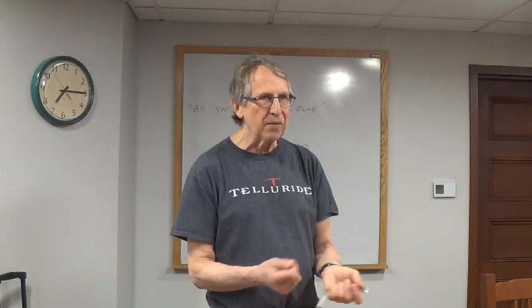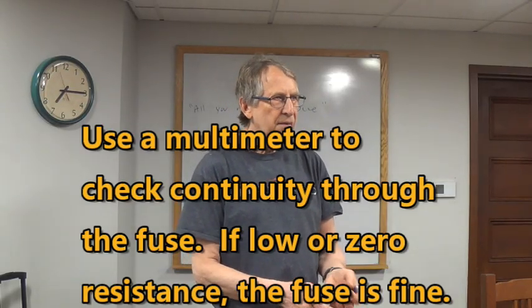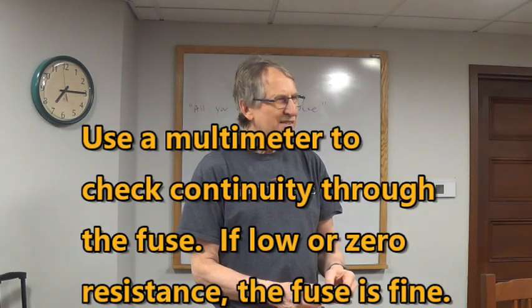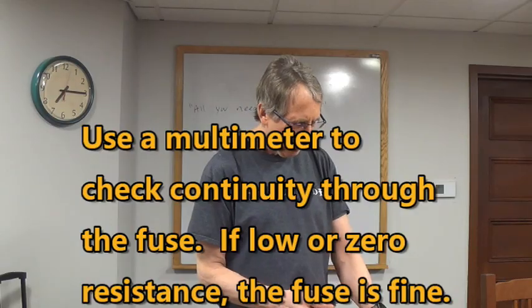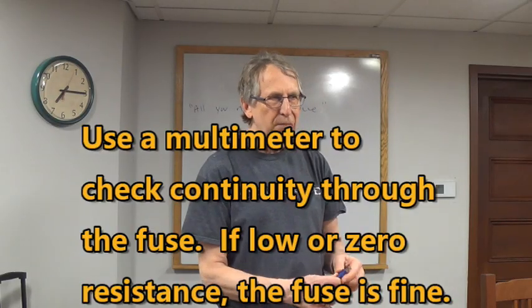Is it present? Is it blown? And you check the fuse with a multimeter. If it doesn't have a fuse box in the plug, chances are it doesn't have a fuse. It may have a thermal fuse. For example, this has a thermal fuse, no fuse in the plug.